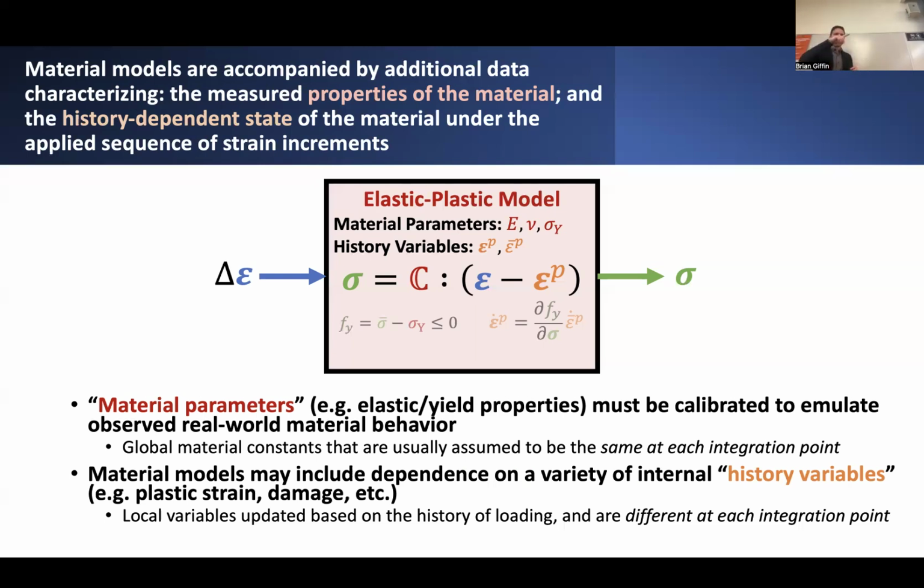So as we continue to update the stress in the material, as we go over different load steps, we might find that these internal variables held by this material model will be updated, or changed, to reflect how the internal state of the material has changed due to whatever loading we've subjected the material to.